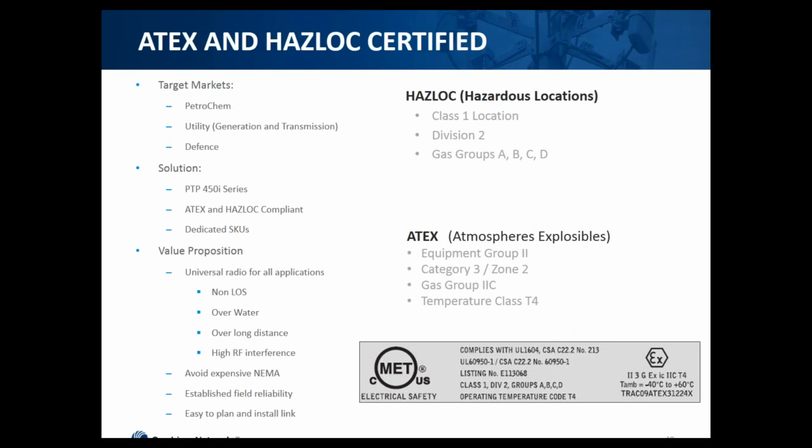So the PTP450i is ATEX HAZLOC certified. So what does it actually mean? HAZLOC stands for hazardous location, and these are classified as classes and gas groups with which the product can interact. So we have the Class 1 location, Division 2, and gas groups A, B, C, D, and we are certified for that.